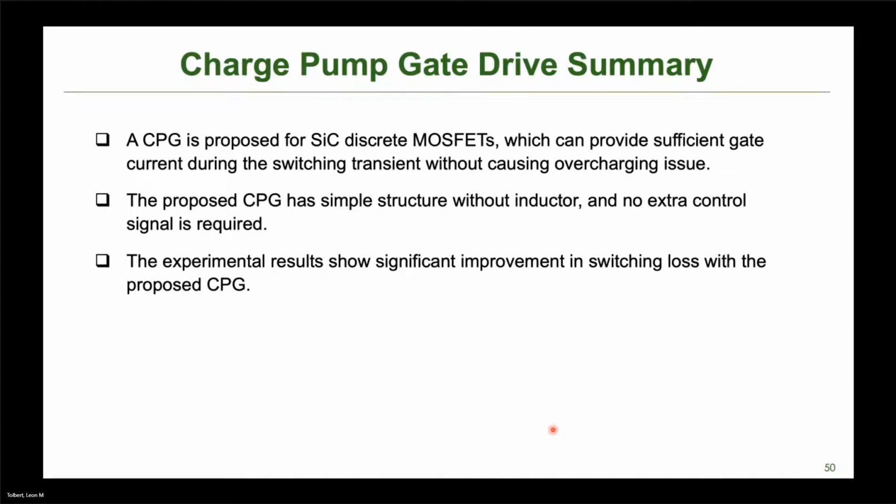You choose a certain capacitance and that helps you dump in a certain amount, but yes, the RG is part of that, and so you may very well want to change that capacitance based on your external resistance as well, as opposed to doing all your calculation for CG and then just playing with RG at the end. You probably want to consider those two simultaneously. Okay, thank you.